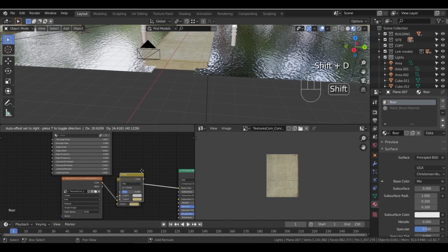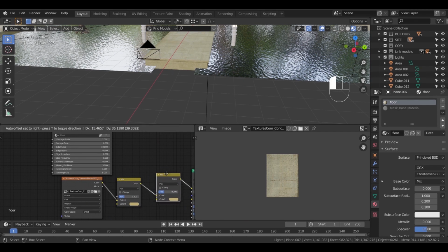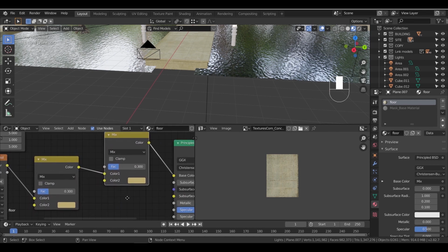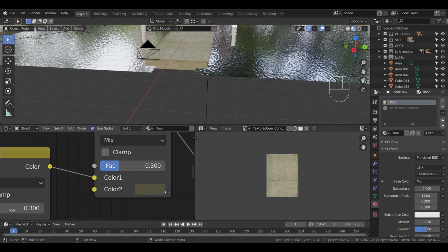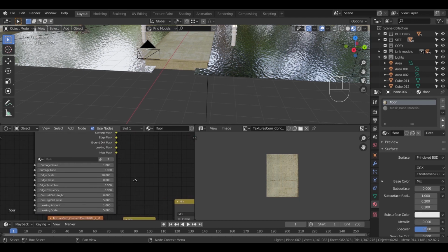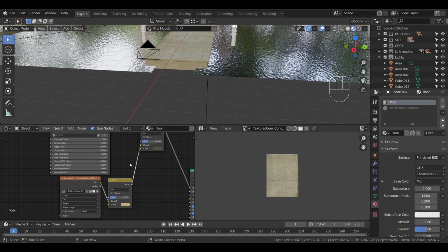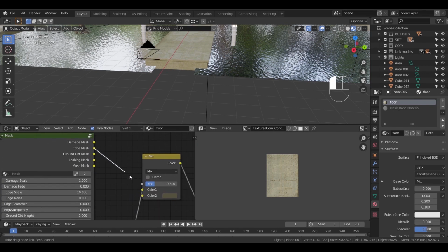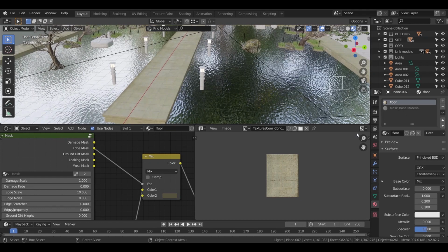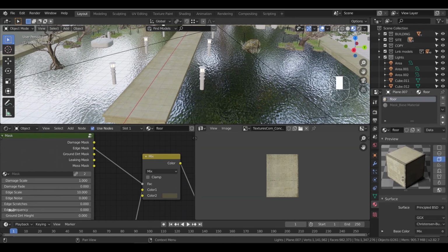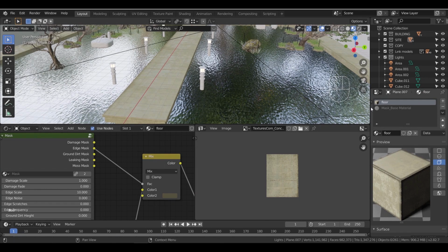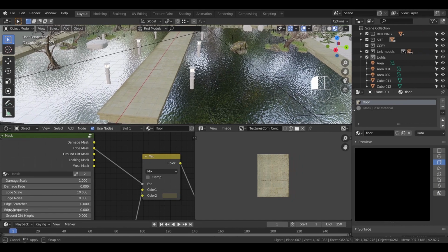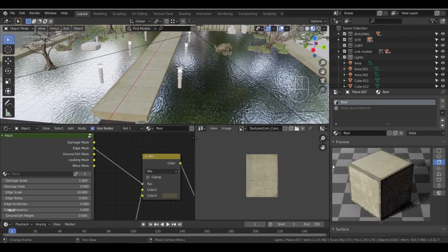After that, copy the color mix node and place it as shown. Make the color toward dark green. We will take this edge mask and connect it to the mix factor. One thing to know is, for the edge mask only, the mask won't appear in the material preview. You either need to set it in render mode, which is heavy to do, or like me, do that in the material setting. Open the preview section to see the change.